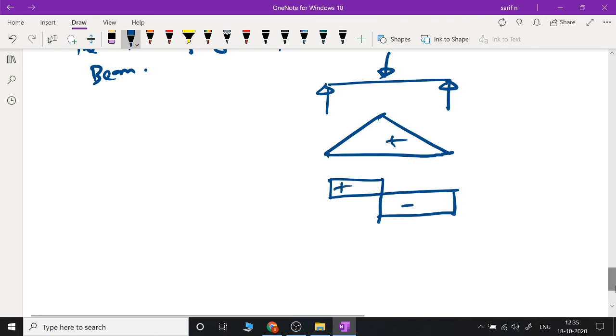We will try to see how to draw this, but basically what I'm trying to explain is what the diagram means. The ordinate here for the bending moment diagram is 0, which means that the bending moment at this location of the beam is 0, and we know that it is an end hinge and the bending moment will be 0. Similarly, the bending moment is maximum right below the concentrated load, and that is at the center. Okay, and at any intermediate point you can also calculate the bending moment by knowing that the variation is linear.